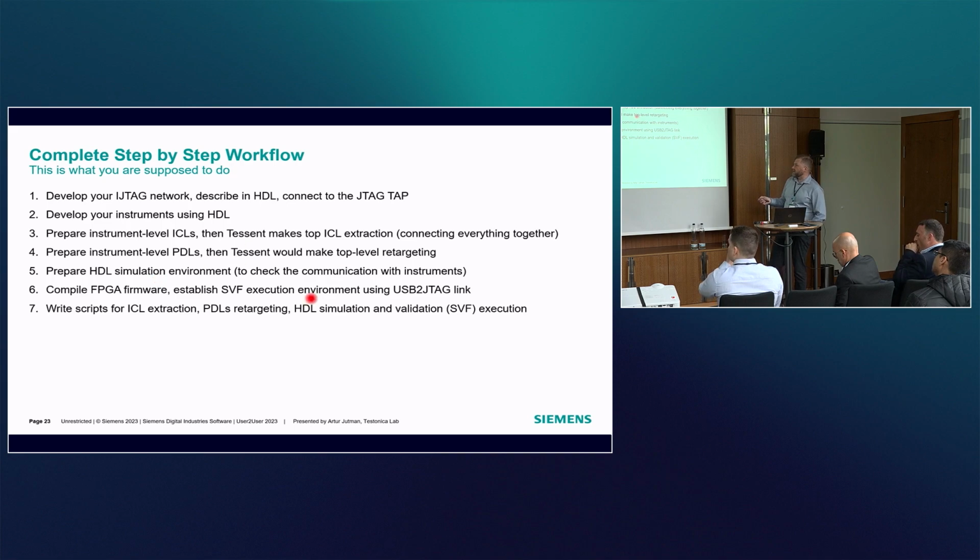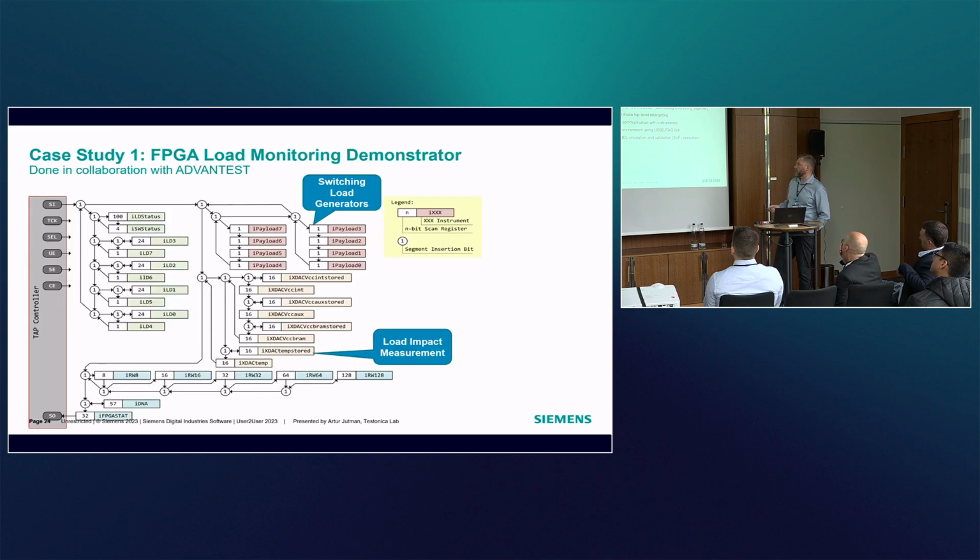Establish an SVF execution environment using a JTAG cable, and you need some external tool for running SVFs. So either you're doing it on a tester like the Advantest tester, or you can use some FPGA vendor tools to run SVF, or basically we use some in-house tools to run SVF over JTAG. And everything requires script development as well.